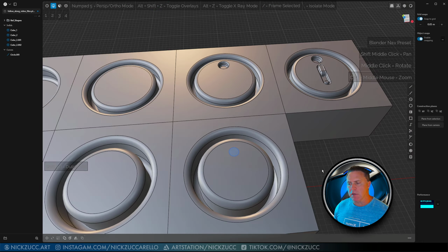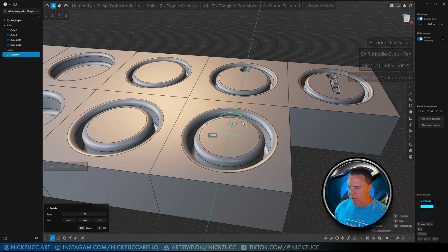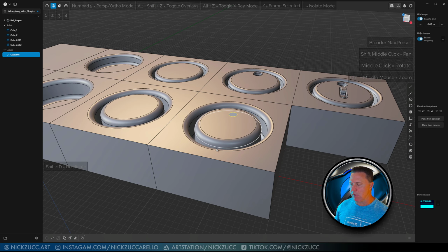If we hold down, let's see if it's shift on here. Let's rotate it. Let's tap R. If I rotate this here, and I've got this at an angle of 90, let's see if it's actually automatically snapping 2-degree increments. And I think that's because I have the grid on. So if I want to not snap to that, I can hold down Control just like we would with the other grid commands. So let's see here. Hit undo. We'll rotate that one more time, and then just rotate that 90 degrees like that, just to show you that we can easily do that and manipulate that.